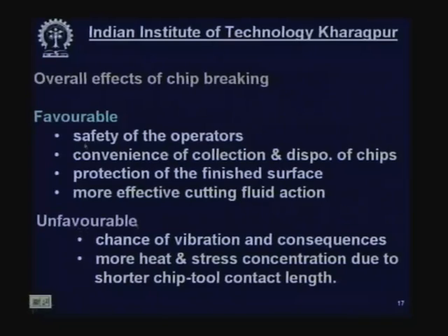Now, what are the overall effects of chip breaking? Let us summarize. There are two types of effects, favorable effects and unfavorable effects. What are the favorable effects? Safety of the operators. As I said, if the chip is not broken into pieces, if it is allowed to move very fast like a sword, a hot sword, as I told you as an analogy, then it will be very dangerous